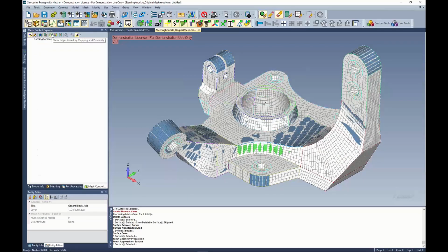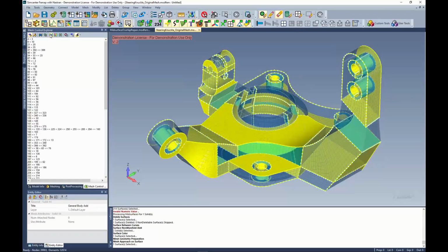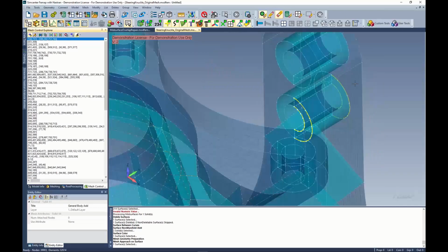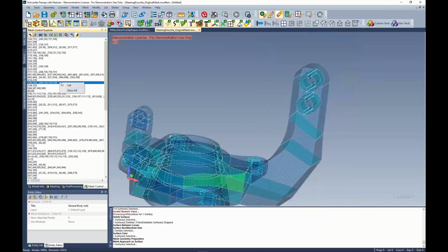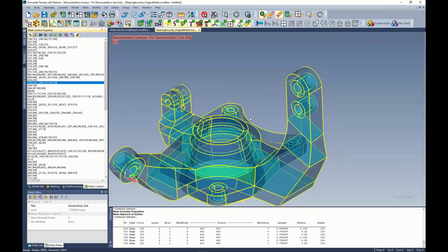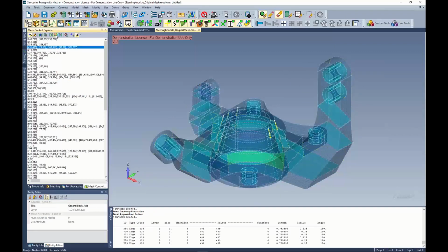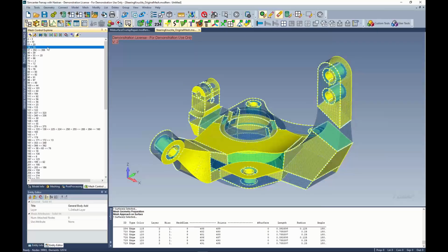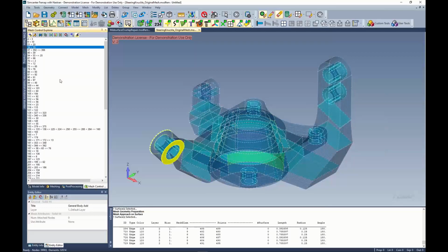There's also a lot of different categories. So I can actually show all the curves that are connected together or mapped together and paired. So this shows you the curves that it'll map between. And then you can list them. You can show all the curves, that type of thing. And there's a lot of different options. Like this will show you the unpaired free edges that are adjacent to other edges. Maybe if you're looking for problems in your model, like something isn't mapping properly. So yeah, I think this will be really helpful for hex meshing in general.